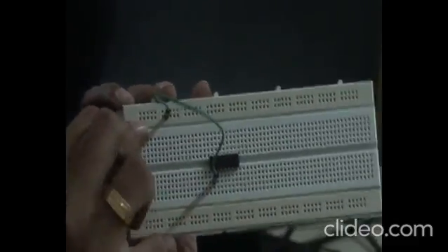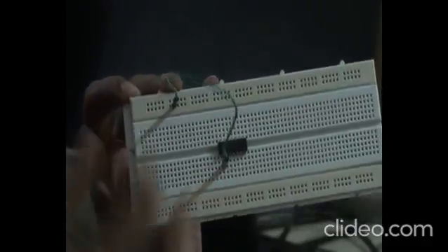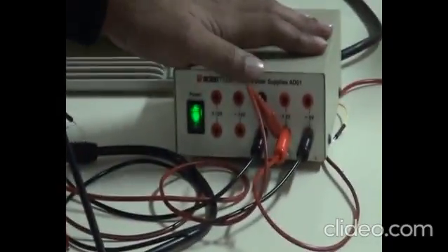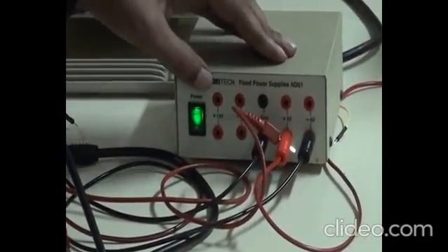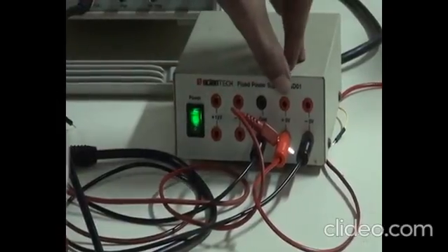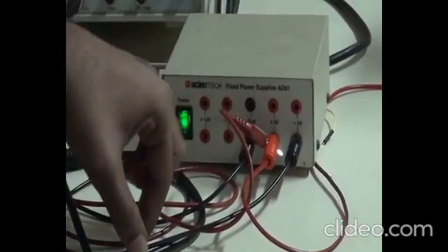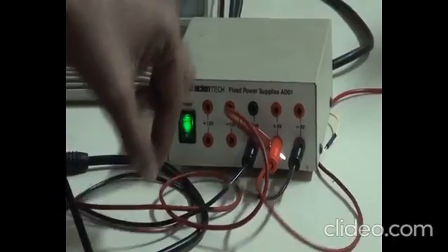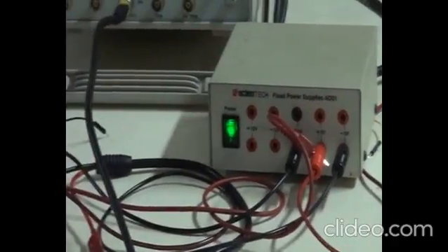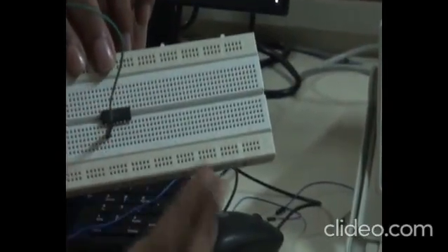And this top point is where I will be giving minus 5 volts required for the IC. And the power supplies I will be taking from the power supply generator. So the power supply generator can give you plus 12 volt, minus 12, and plus 5 and minus 5. And this particular minus 5 connection I will take from the power supply, and I will connect it to this particular point. So that's how you usually connect an IC and power supplies to the breadboard.